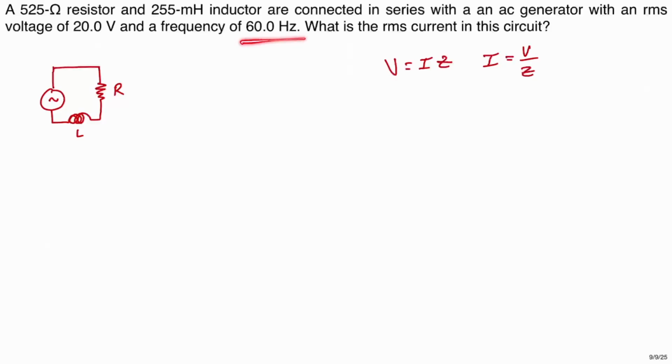They gave me the frequency, 60 hertz. Great. So how do I find the impedance? Big square rooty thing, right? The square root of R squared plus XL minus XC quantity squared. That's supposed to be a C. So that means I have to find what the XL and the XC is.